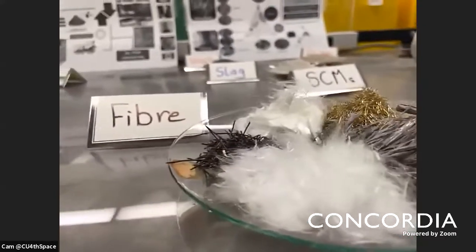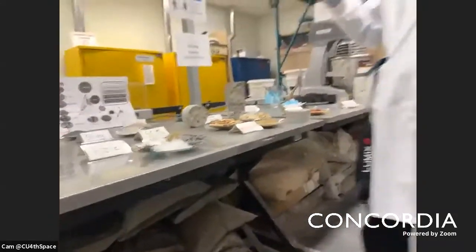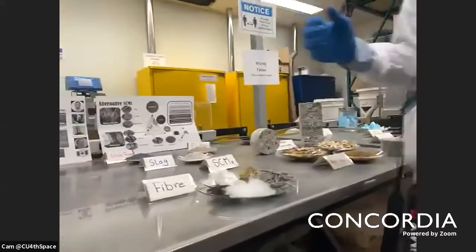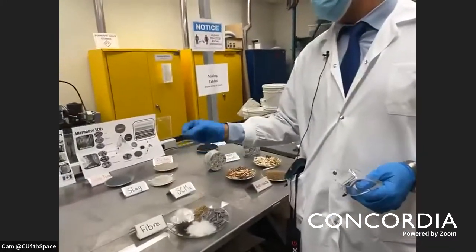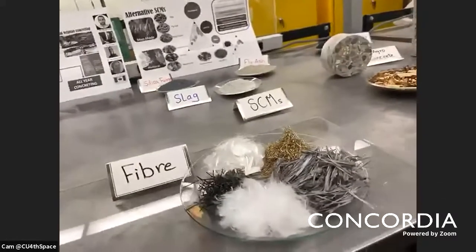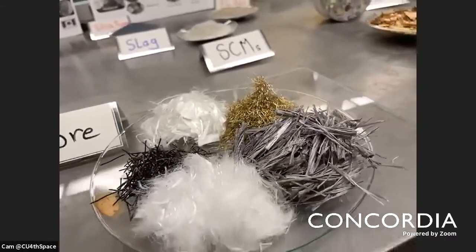Each one will have an effect on the tensile strength, but at the same time will affect other properties. For example, if you add too much of this one, you are expecting to have harsh concrete, not flowable. Okay, if you add too many fibers, it can get tangled inside and leave voids. Okay, so it's something you have to do by trial: how much of this fiber will give you the desired result.